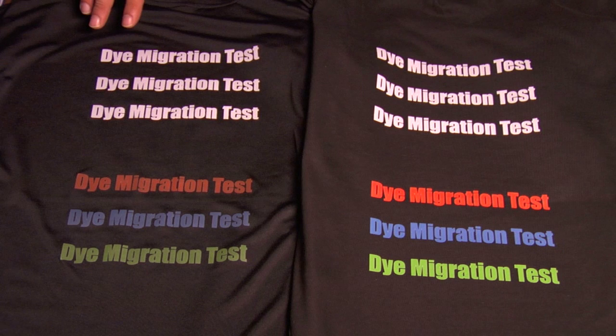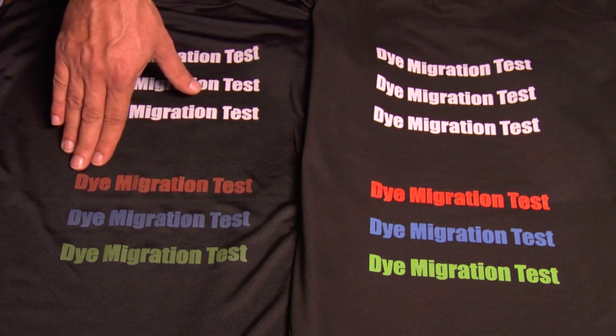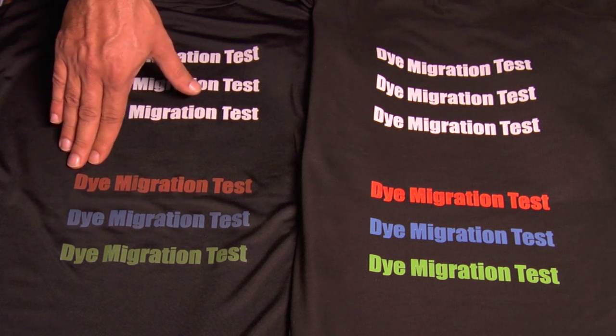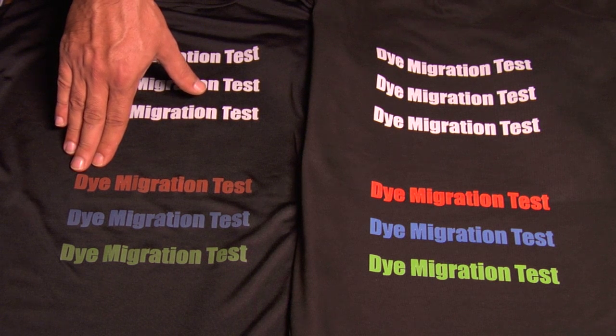The reason is because with the Concert T, the white base is at the top. So we've got a toner layer separating it from the polyester. But when it comes to the laser dark product, the white base is right against your colored polyester material. And if that happens, odds are you're going to have a fair amount of dye migration and it's going to distort your image. Let's review what we've learned today in regard to opaque materials and dye migration.